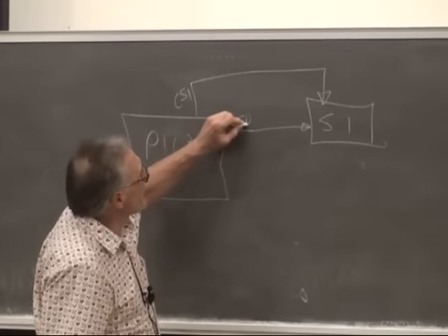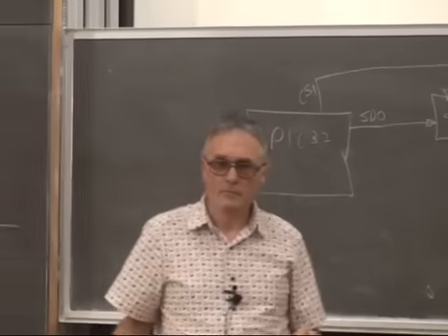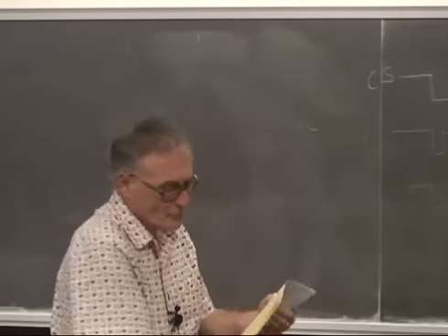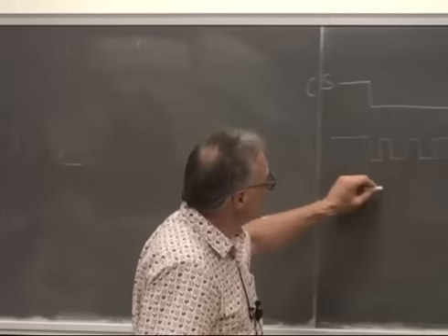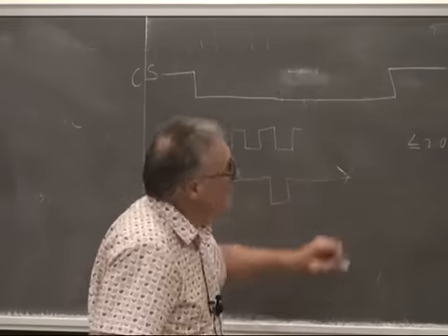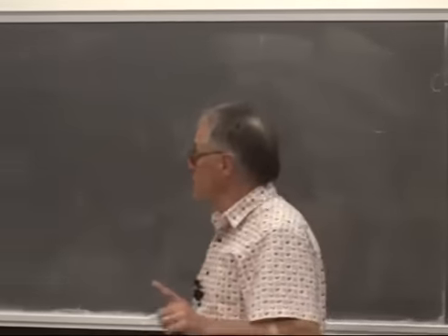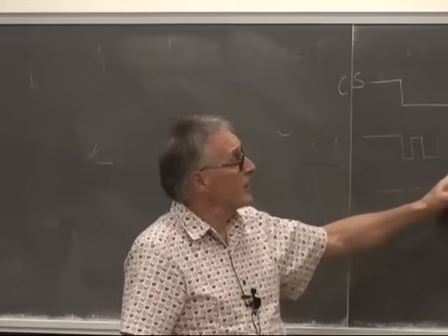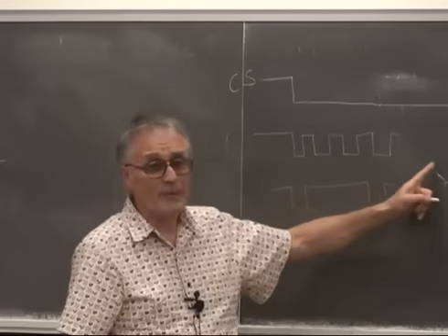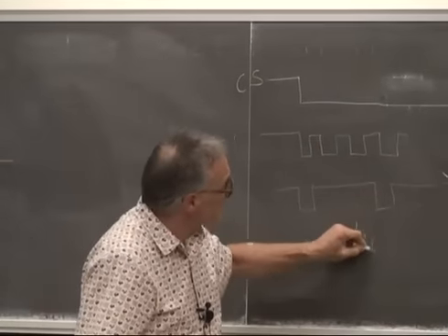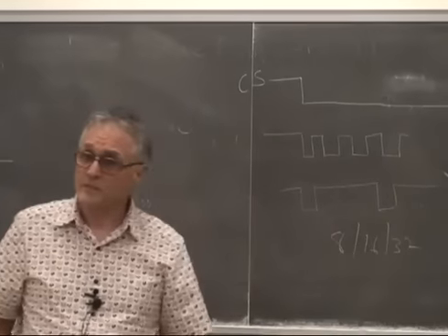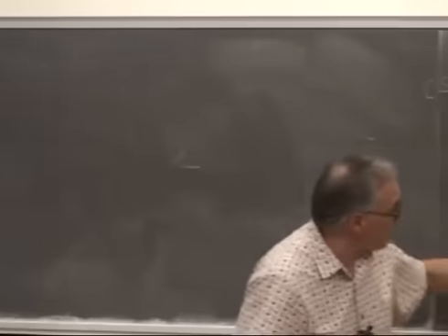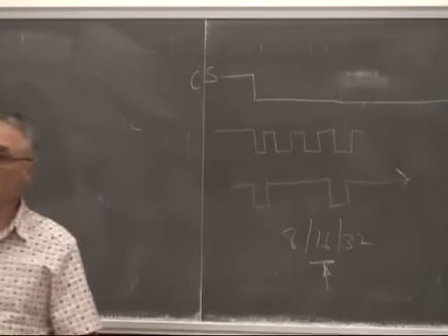what is it called on this chip? SDO. Serial data out. You can set on this particular chip the transaction length, the number of bits, set to 8, 16, or 32 bits. For this lab, we're going to set the transaction to 16 bits because that is what is required by the DAC.